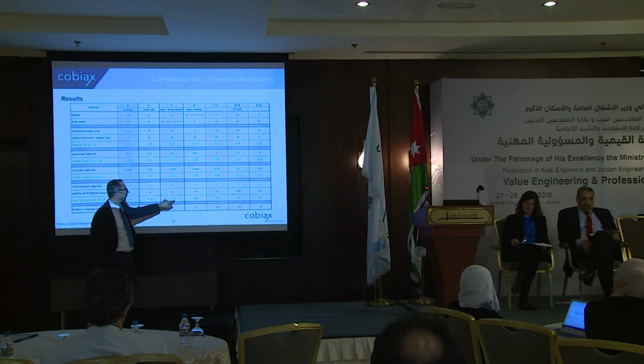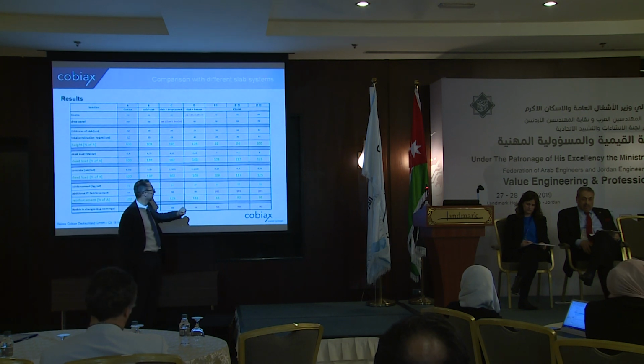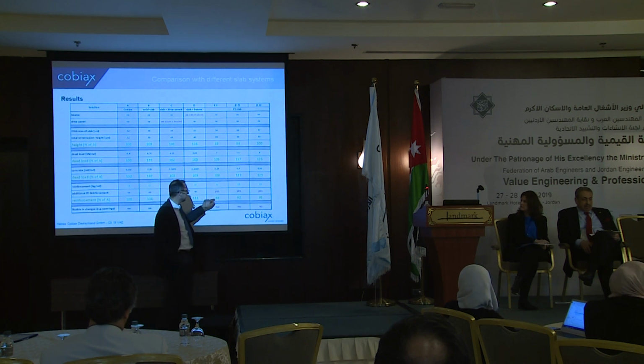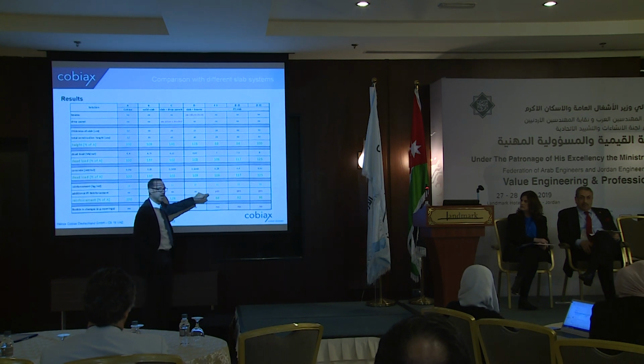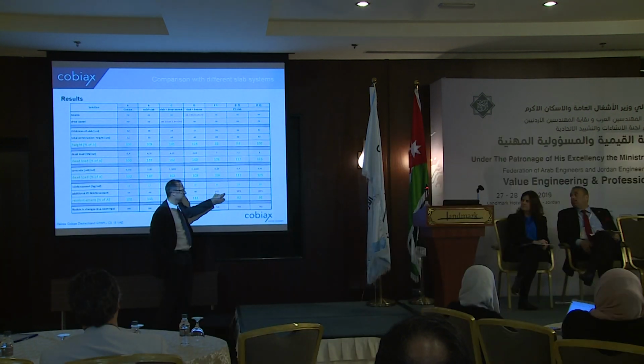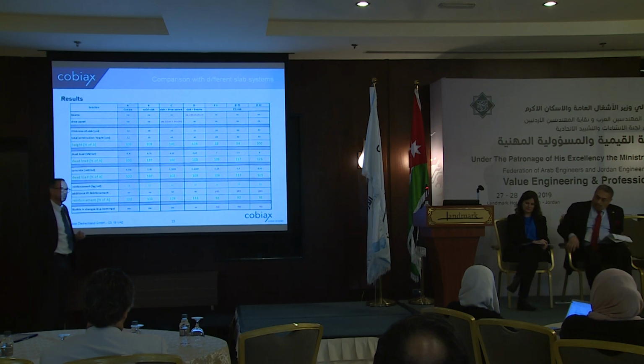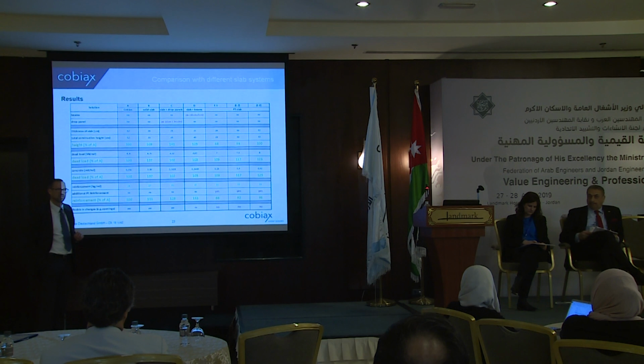29% increased amount of reinforcement for the slab drop panel combination, then the slab beam combination, 11% more reinforcement. And here you will see the amount of only the typical reinforcement for the PT solution, 86%, 92%, and 96%. But you have to take into account that you have to add the PT steel as well. I haven't calculated it here. I only have pointed out you need additional post-tensioning reinforcement. That will make it more expensive at the end compared to the solid slab.